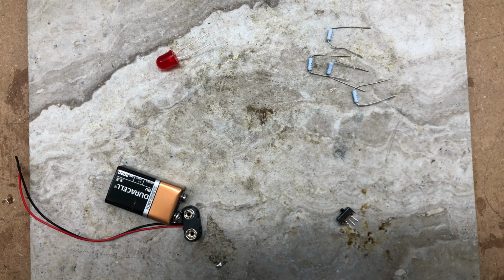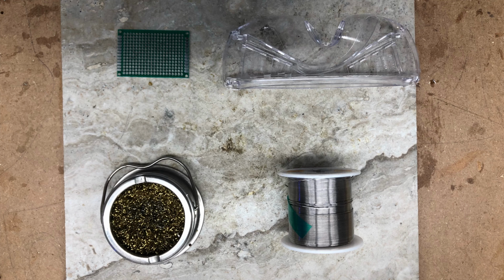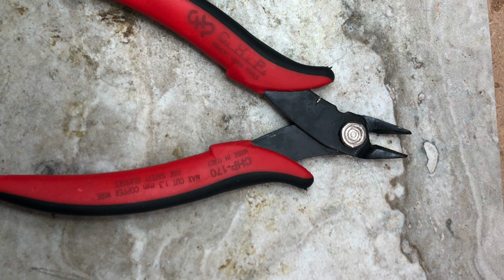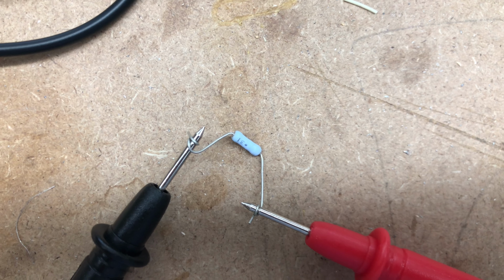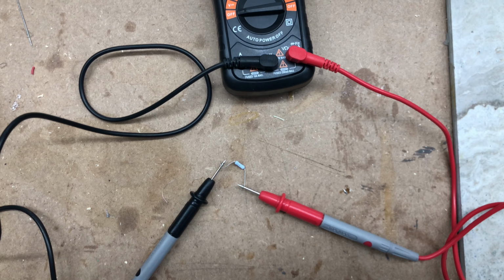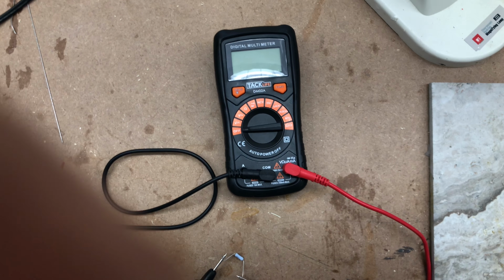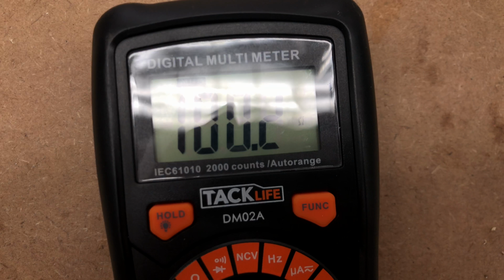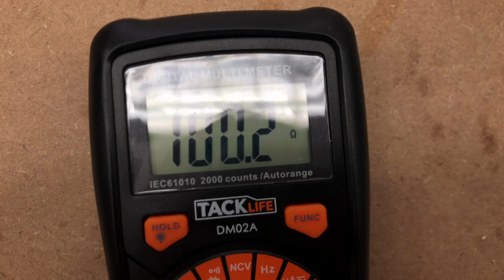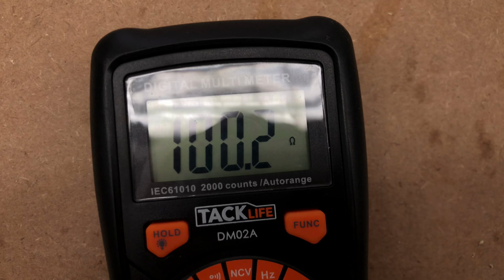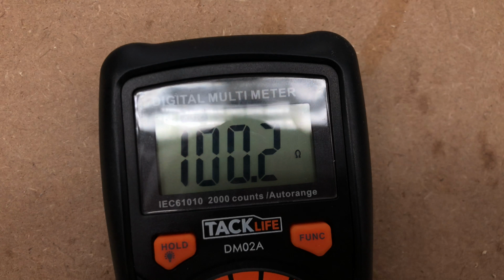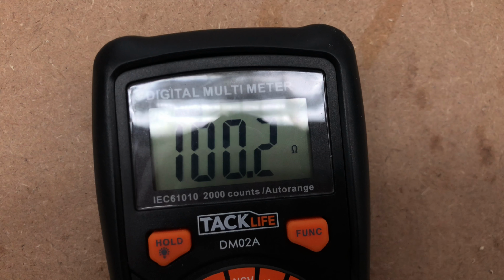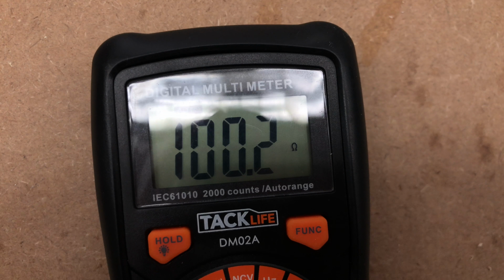The final step is to create a physical rendition of your circuit on a proto board. Gather your components: a soldering iron, a proto board, goggles, steel wool, solder, a multimeter, and pliers. To find the resistance of a resistor, connect the resistor's legs to the probes and set the multimeter to the ohm setting. Since this is a 100 ohm resistor and resistance adds in series circuits, I use 4 of these resistors to create 400 ohms of resistance, which fits the calculated 350 ohms.